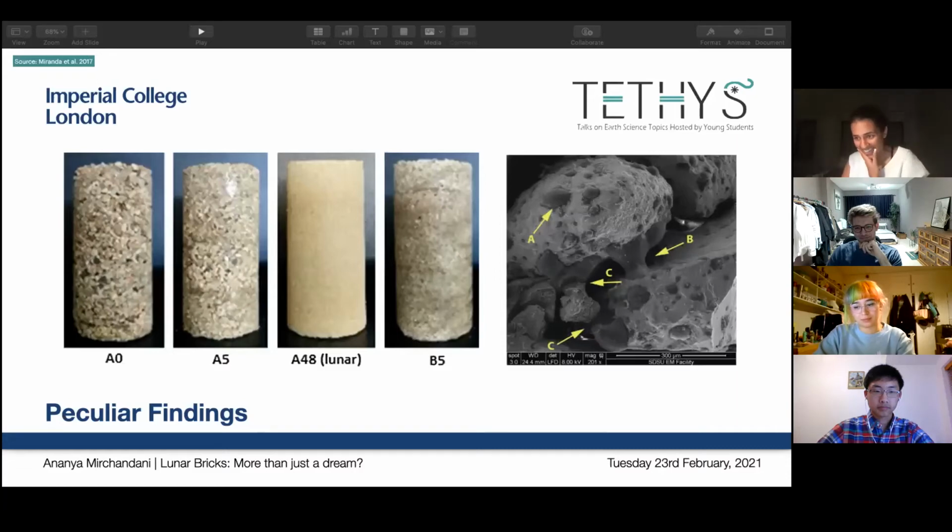On the other hand, we also have a more extensive research conducted by Miranda et al. in 2017, who investigated the addition of thermoplastic polymer particles to facilitate the bonding of soil grains. What they learned is that gradation of the regolith is actually so important, because finer grain would enable more efficient polymer distribution at intergranular contact places, which is where the grains meet. So sorting grain size is an engineering problem.